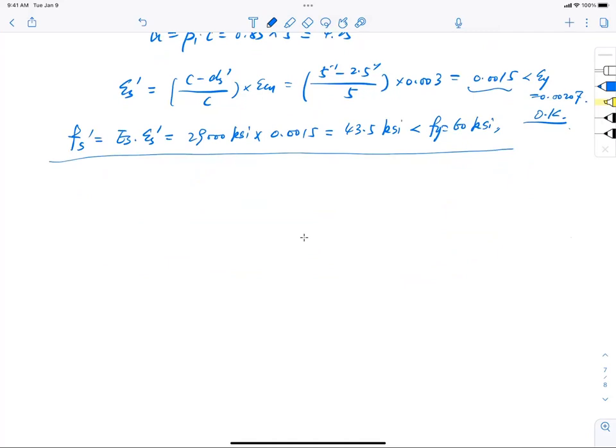All right. Like I said, this is pretty dry so far. So you're just going to carry on, find out the compression force from the concrete, and Cc equal to 0.85 f prime c a b, no surprise, using the equation. So 0.85, plug in the number 4 ksi, and a equal to 4.25 inch, and b 12 inch. So I got this number to be 173 kips.